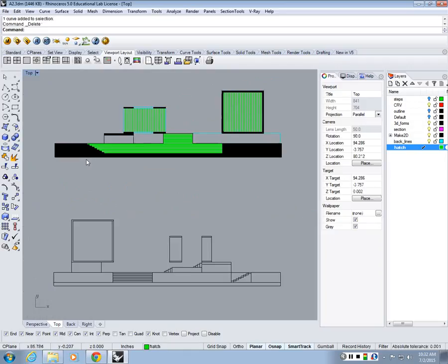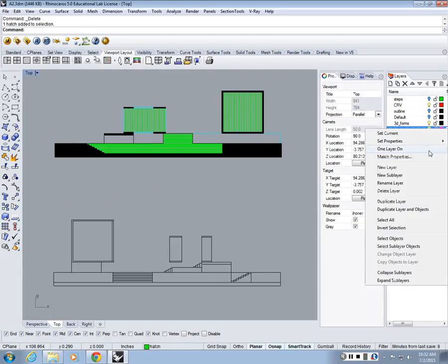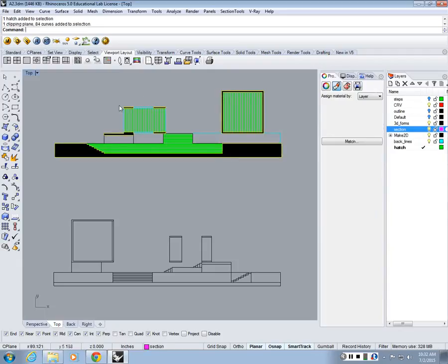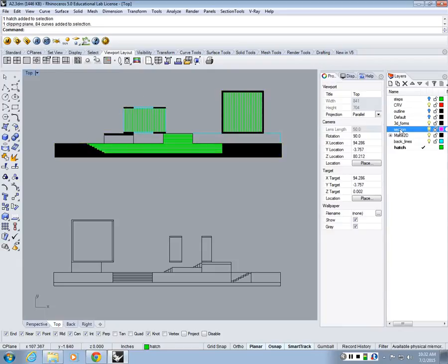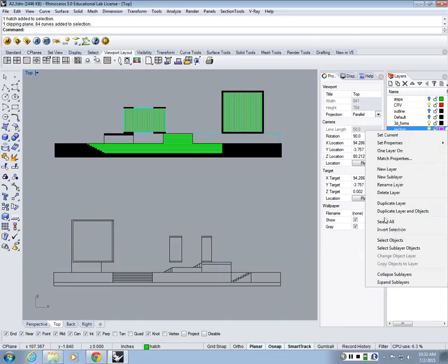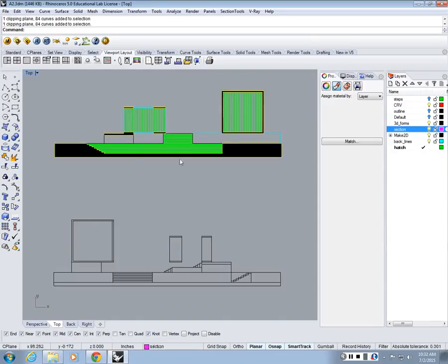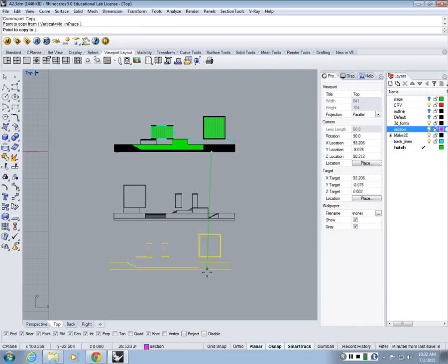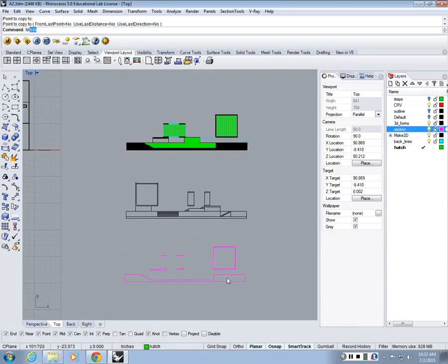And what I'm going to do is grab the section lines here. I'm selecting them through the layer they created. So I right click the section, do select objects. So I grab those and make a copy of them here. And I'm going to do a mirror because the section, we flipped the direction, right? So it's going to look into the other view. I'm going to mirror it. I'm going to turn copy off, so I'm going to make it no. I'm going to just draw a perpendicular line.